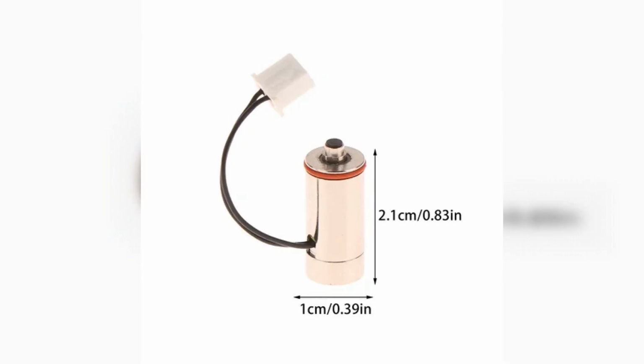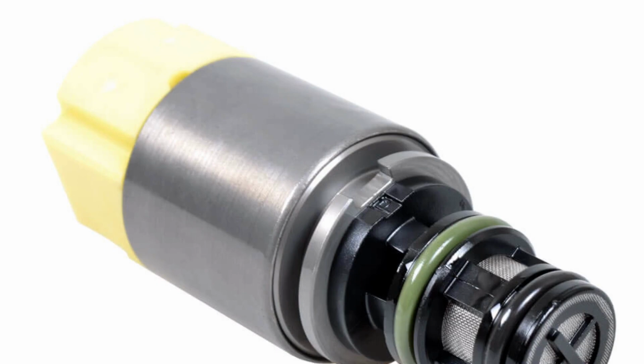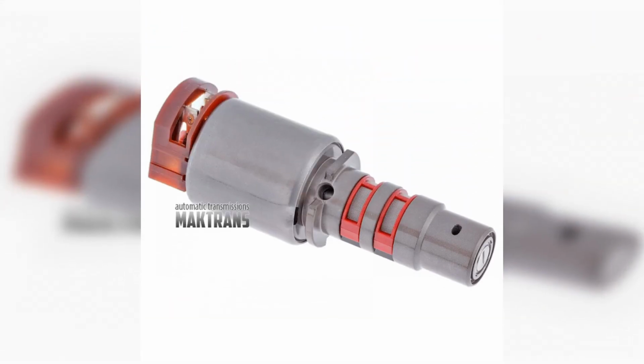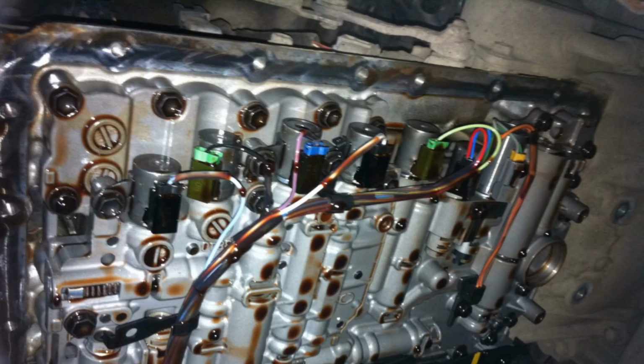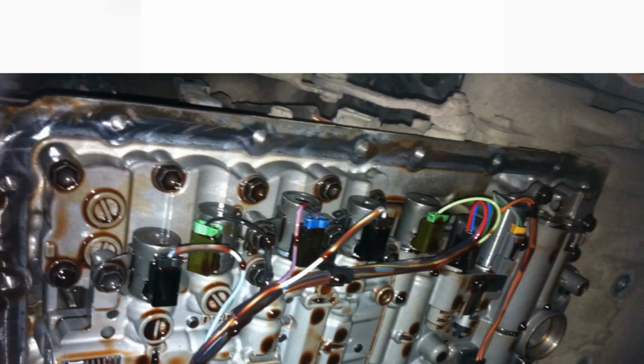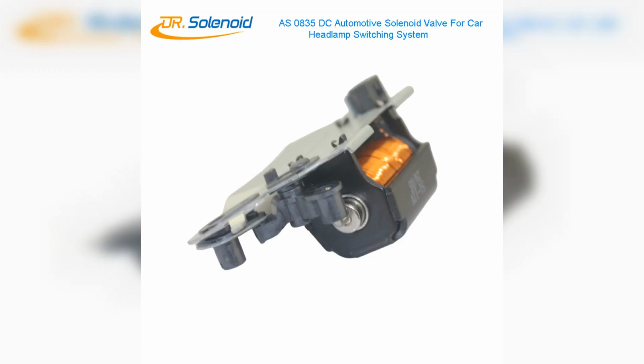A detailed visual inspection should then be carried out, along with a check of the wiring to detect any obvious defects. Check the connectors and wiring going to the shift solenoid valve, transmission pump, and PCM. Depending on the configuration, the transmission pump can be electrically or mechanically driven. Normal readings for cables and connections should be 0 ohms of resistance. Wiring continuity checks should always be carried out with the power disconnected from the circuit, to avoid short circuits and creating additional damage. Resistance or lack of continuity indicates faulty wiring that is open or short-circuited. In this case, it will need to be repaired or replaced.